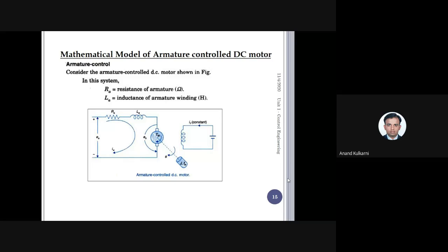Another disadvantage of a DC motor is that the power source is DC, so its direction is constant. The motor rotates through 180 degrees and then reverses back. That means you will not get a complete rotation, only half rotation is possible.